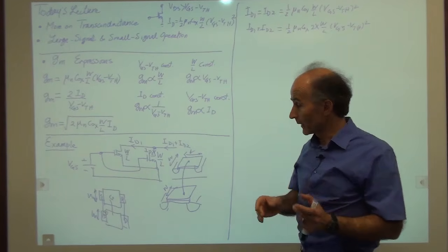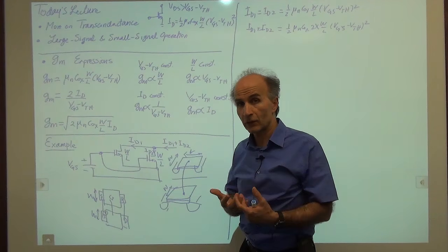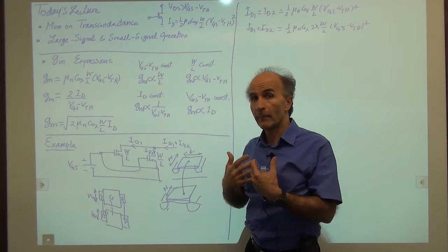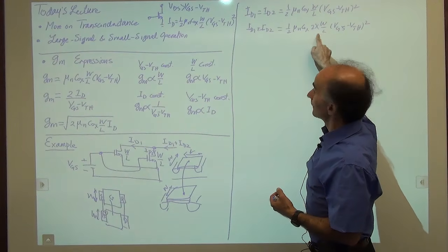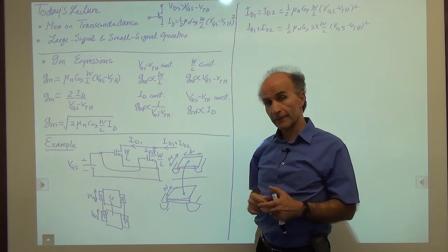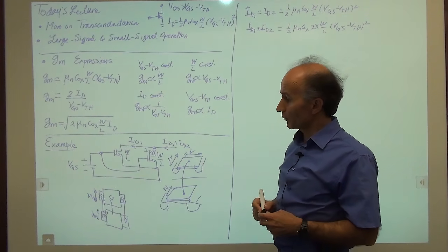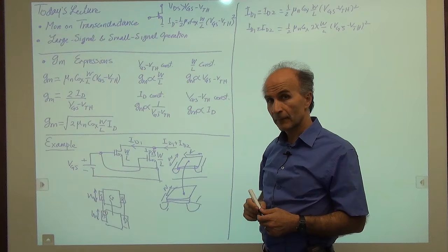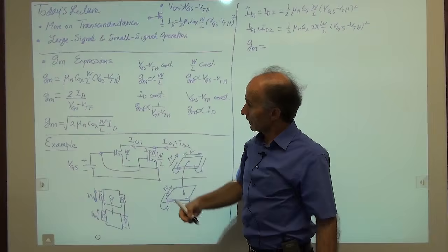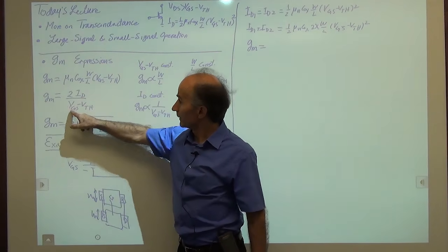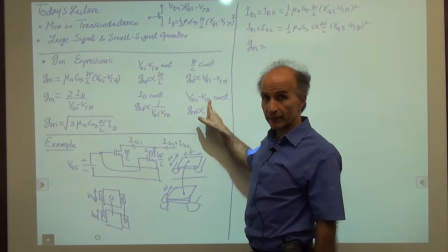It's the same for both of these devices. So equivalently, if I want to put these two devices in a black box, the only equivalency I can create is to say the new composite device is twice as wide as each of these devices. All right? Okay. So now what happens to the transconductance of the device? Well, we write GM. We can try to use any of these. Perhaps the simplest one is this one, because we kept VGS minus VTH constant, right?